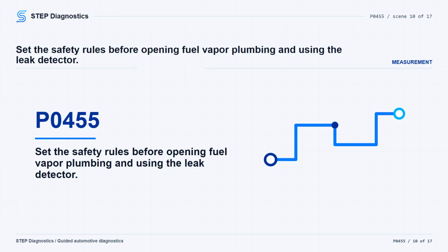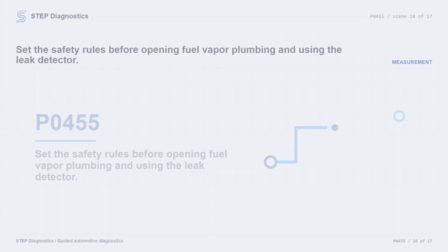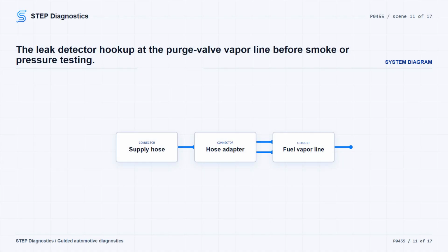For the leak detector, use the evaporative emission leak detector with onboard nitrogen generator 218-522C or an equivalent tool. The fuel level in the fuel tank must be less than 85% full for this equipment. Do not apply smoke to the EVAP leak detection control module.